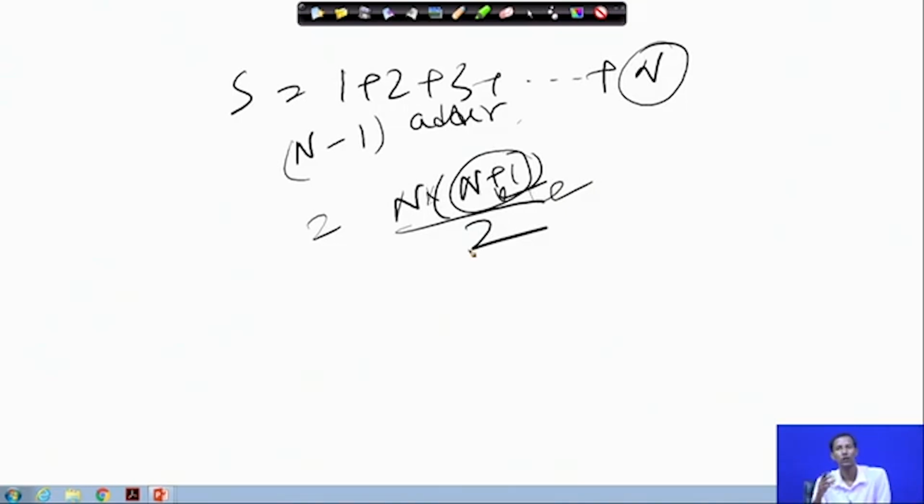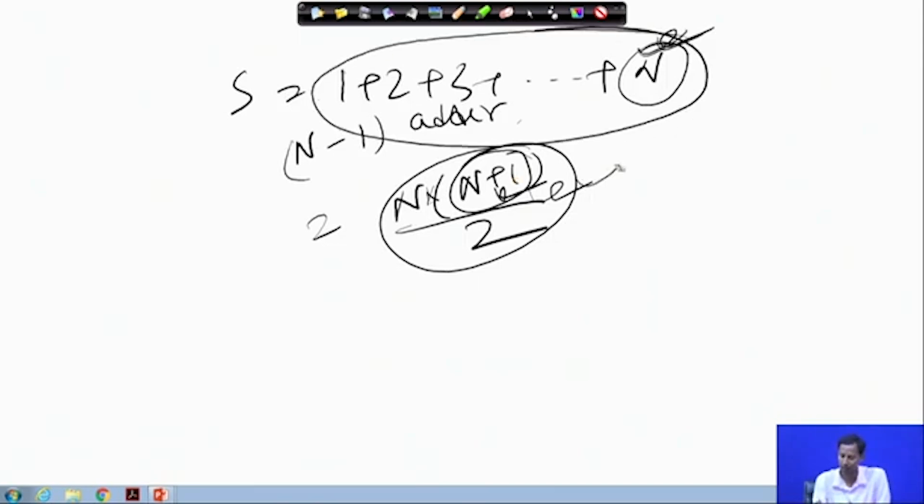That means, it will not depend on the value or the length of n, it will not wait for that many clocks. Within one clock, if I just want to get the result of this, at that time I have to implement this kind of architecture. At that time the circuit required is more. Here I require a multiplier and here I require an incrementer circuit.